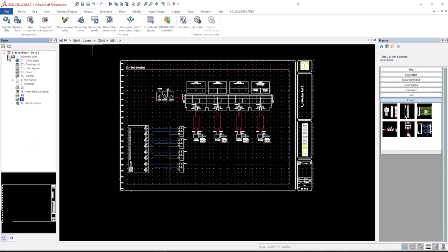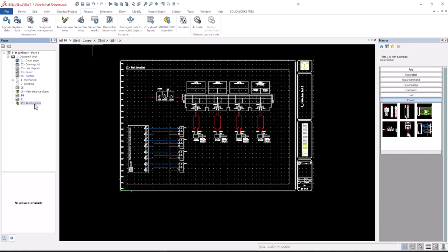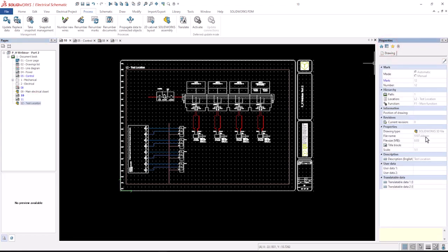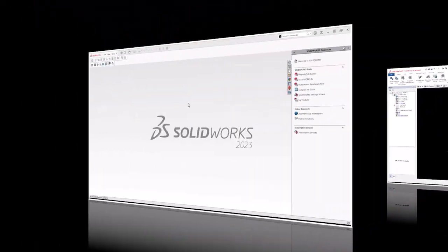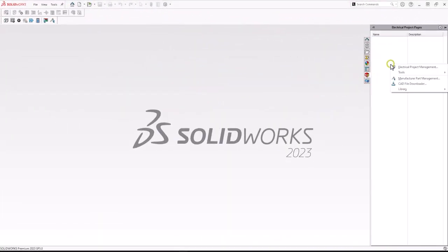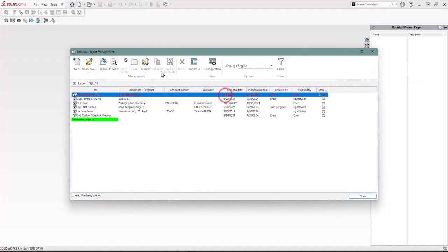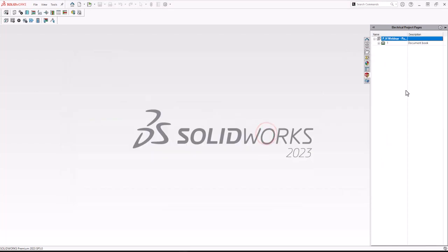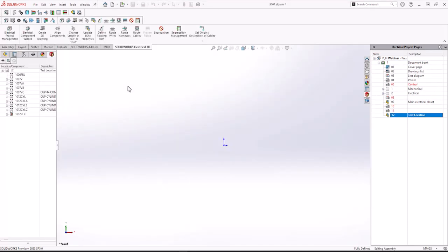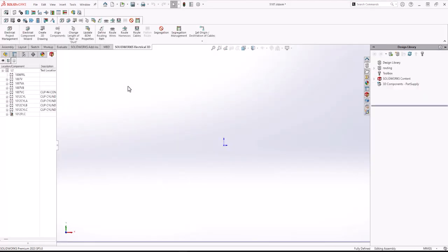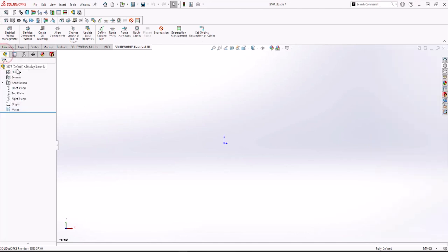When I look at my documents browser, it has a new page. And if I look, I can see a file name for the new SOLIDWORKS assembly. Over here in 3D and SOLIDWORKS, I'm going to open up my schematic project and be able to go to that new link of page 12. And when I do in SOLIDWORKS, what it then does is open up an assembly. Now that assembly on my feature tree will call out that same name that I had on the link from my schematic process. And then at the same time now in my browser, I have all those devices.